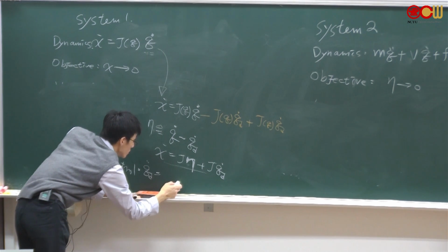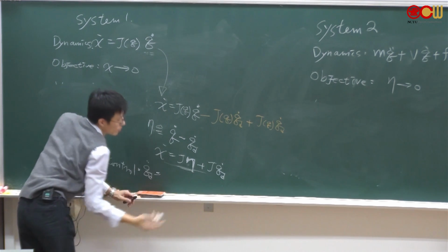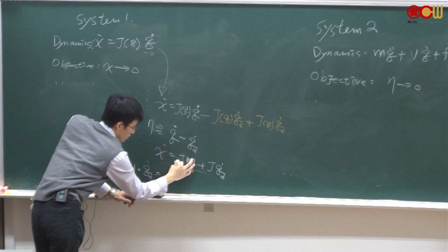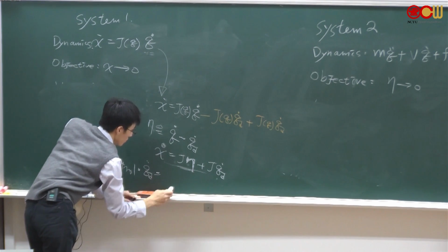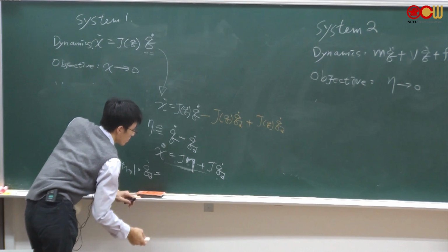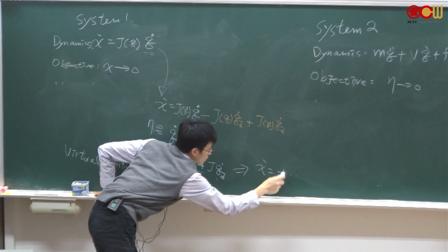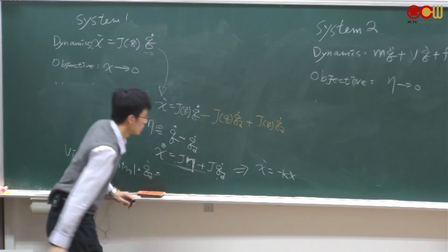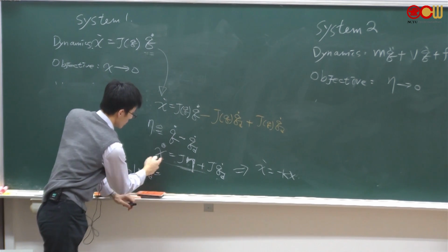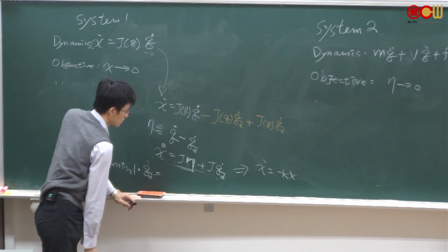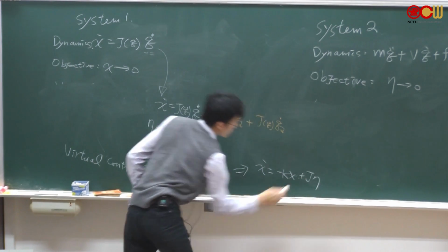You can say I want to design QD dot to be a feedback term, right? This term will eventually become a cross term, so just let it be, and you design this term for this system to be stable. So simply use a feedback term in the virtual control. And remember, you keep this term because that will be a cross term.